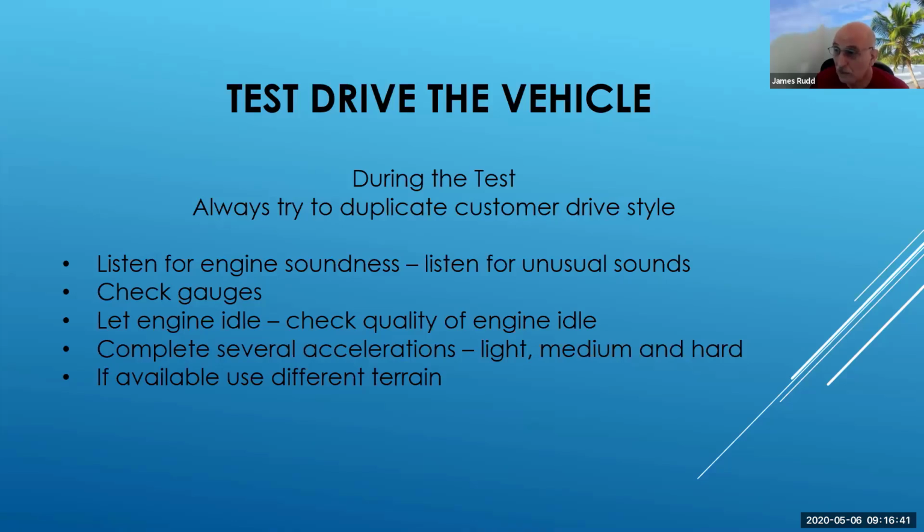During the test drive, always try to duplicate the customer's drive cycle or driving style. Some people drive differently than other people. So listen to the engine soundness, like I said before, look for anything unusual, check gauges, let the engine idle, and check the quality of the engine idle. Complete several accelerations, light, medium, and hard, trying to get maybe that breakdown.